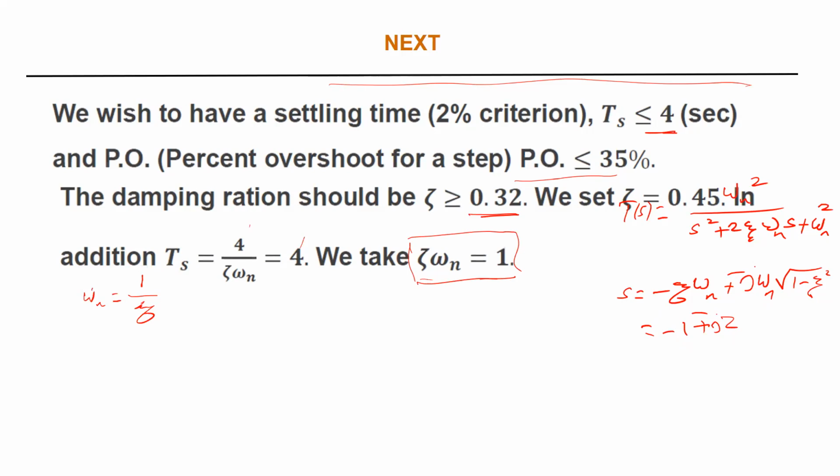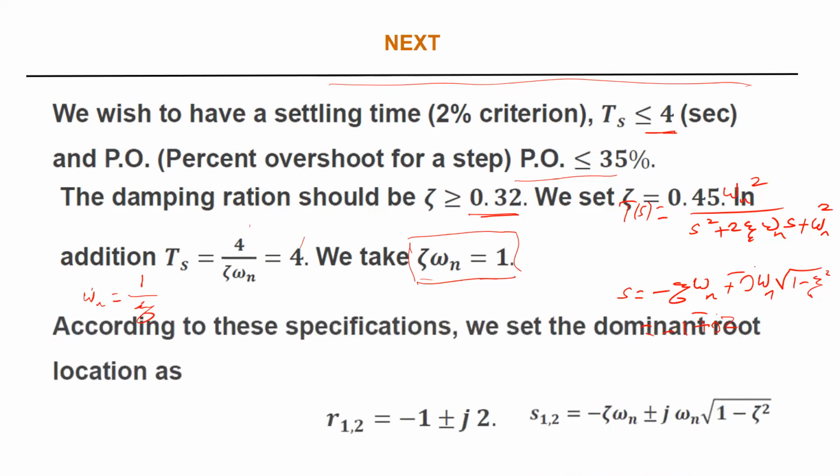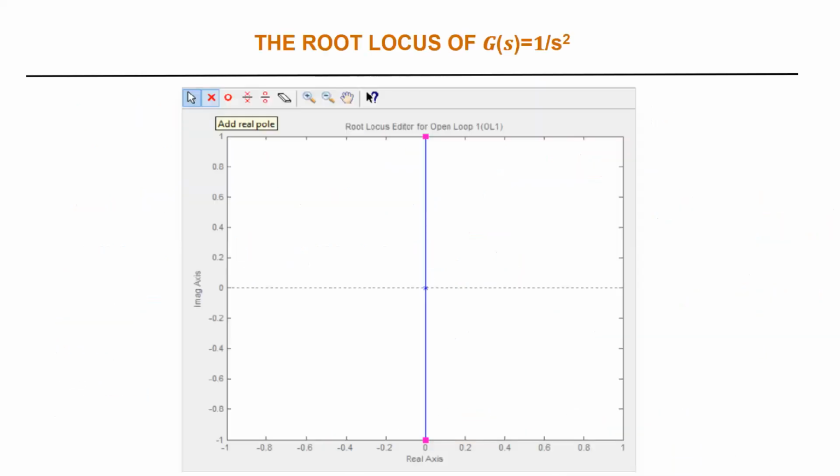Now, let's take, okay, this is the root locus of the open loop system. And, you know, the scale in here is very small, but assume that the location of the poles go to the desired ones, one here and one here. And definitely they are not on the j omega axis. So, do we need a compensator? Definitely, yes. We need a compensator.